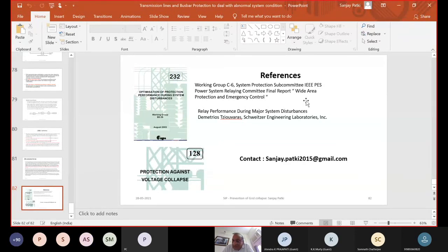Basically, this has been a problem because of mercury switches. I don't know about Nanded; Nanded also had a severe earthquake in those days, in 1997-96, and this case was in May 1997. It is actually experienced by many people where an earthquake or any other big movement occurs. The old Buchholz relay had a mercury switch which gave alarm and trip, and if there is a big shake-up, the mercury flow will initiate a trip.